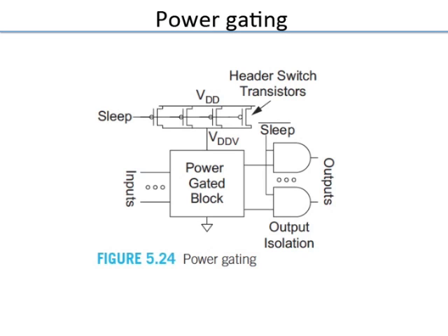So that estimation of I is a tricky thing because I can have two gates switching in the same cycle, but if they are spread out in time, the currents are low, the peak current is less, but if they happen at the same time, the peak current is double, right? So that is the complication because the actual time of switching and the number of gates switching, all of that have to be considered, and the time of switching depends on the actual design and layout and so on.